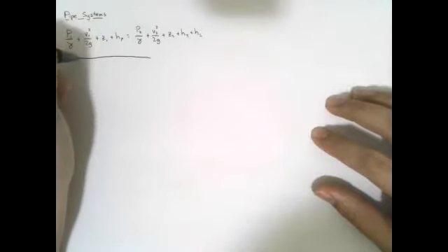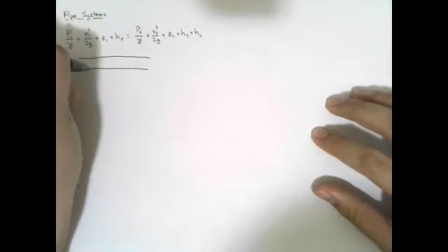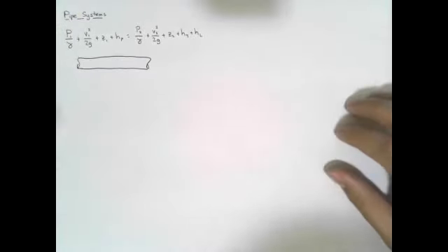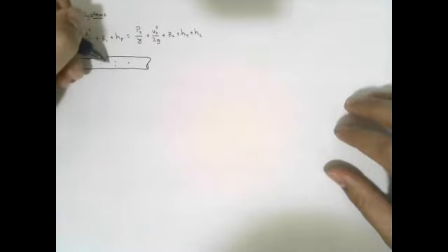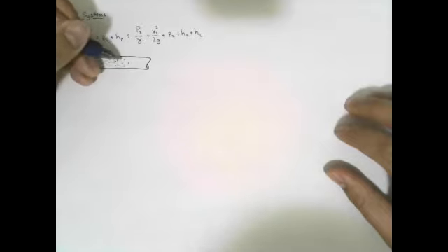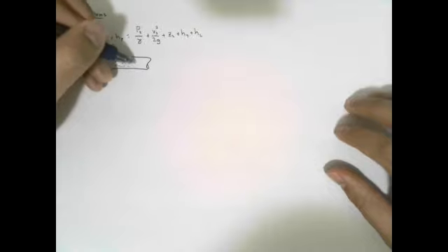Now, if we look at turbulent flow inside a pipe, if I were to ask you to compute the velocity profile of a fluid particle, we're going to have a hard time doing that because, like I said, that motion of fluid particles may seem to be erratic. So you may have different particles moving in different directions with different velocities. And you're even going to have streamlines that intersect, right? You're going to have mixing, what's called mixing.